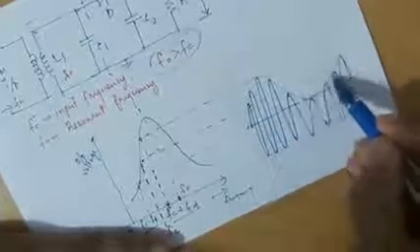So whenever the frequency Fc plus Fd changes, correspondingly there is an amplitude change in the output waveform. What we are doing is converting linear frequency deviations into voltage deviation. That means we first have an input signal that has only frequency variations, but the amplitude is constant. By giving it to the frequency selective network, according to that frequency deviation there is a change in amplitude